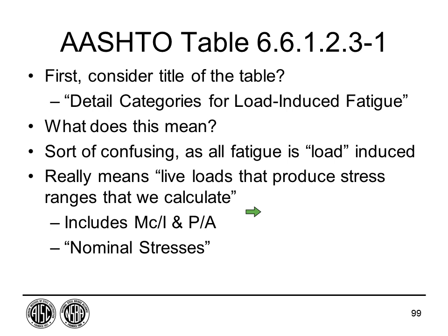So first thing is when we look at the table, we have to think of the title, and it's called Detail Categories for Load-Induced Fatigue. Well, it is a little confusing, right? If we say load-induced or live load-induced, because you might think, well, it's all live load-induced. Well, that's not really what we're getting at. What the table is getting at by load-induced is stress ranges that we calculate. So this is your bending moment in a girder, Mc over I, P over A in truss members, whatever, but stresses that we calculate. Nice, simple, nominal stresses. We don't worry about the hot spots, like we said. That's all built into the details.